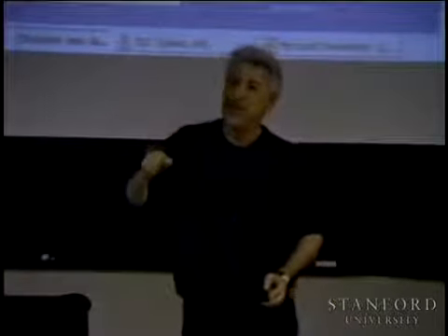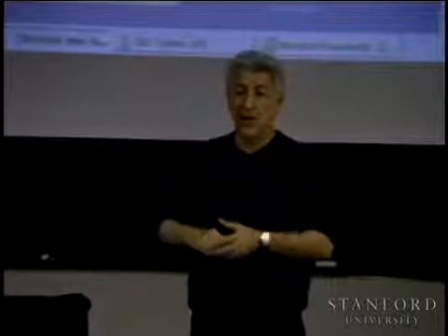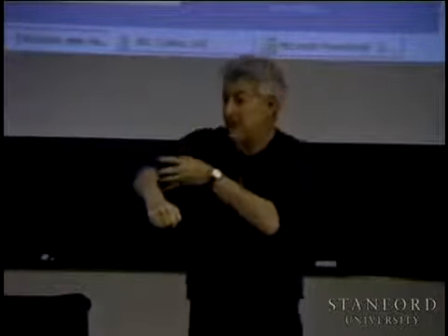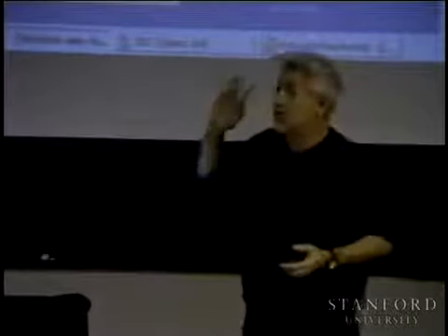Well, the forward kinematics gives you the location of the hand. The inverse kinematics gives you, given a position for the hand that you desire, the joint angles you need. And if you do that, then you know your goal position angle for each of the joints. Then you can control these joints to move to the appropriate joint positions, and the arm will move to that configuration. Well, can you do inverse kinematics for this robot?